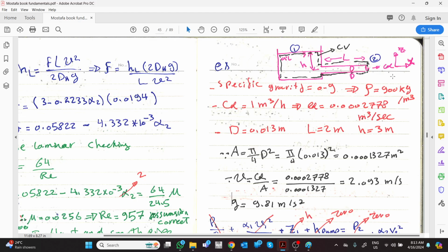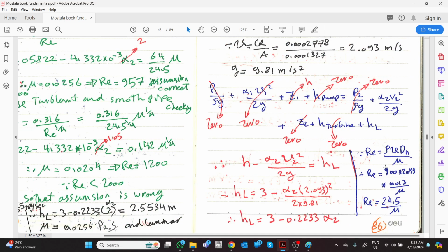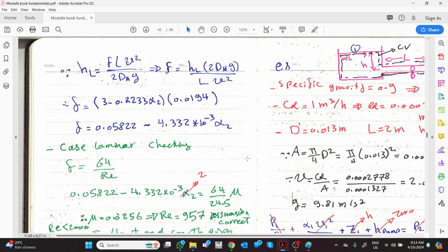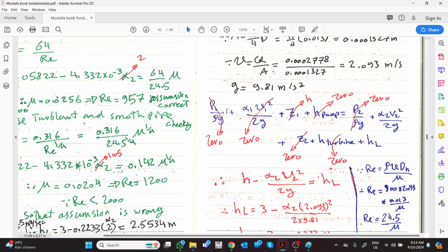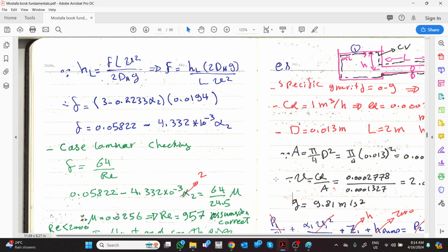You will check what is the flow rate, you check what is the height, you know what is Reynolds number, but it is a function of mu. You will put everything, you don't know what is phi, bear with me. Then you will find the coefficient friction factor. By the way, it is H loss friction factor. Friction factor is equal like this from the H loss. H loss we get it from Bernoulli, by the way. So you get friction factor equal blah blah blah.